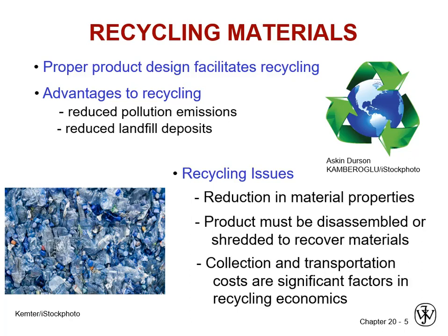Issues with recycling, and we mentioned this with thermoplastic processing. With the exception of your higher temperature materials, metals, and polymers, you will typically get a reduction in material properties, especially again with thermoplastics. Every time you run them through the extruder, you're going to see a reduction in molecular weight. Doesn't mean you can't still use that polymer for a lot of applications, but there's not a one-for-one. So you have to think about, am I recycling or am I downcycling, and plan accordingly.